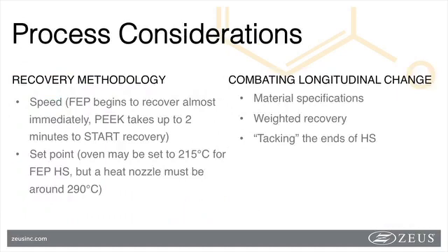Heat source and temperature are not the only factors in the recovery methodology. Speed at which that temperature is applied is important as well. For instance, FEP begins to recover almost immediately at its recommended temperature, while PEEK may take up to 2 minutes before it starts to move.